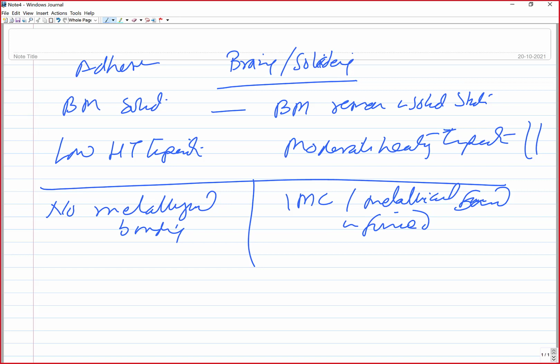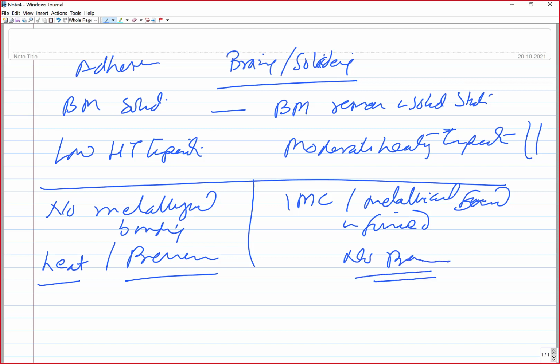Normally heat is used for curing and for proper spreading, to ensure that the adherents remain in position, a sound joint is formed, and the desired thickness of the adhesive is achieved. We use pressure as well; pressure may or may not be used, but in brazing or soldering processes there is no pressure used.